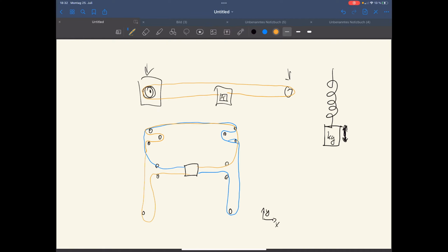So let's assume we want to print a shape like that. And when we are going with our acceleration and speed along that, to that, that to that, that to that. If that is exactly within the time we need here, if that is 1/2f, for example, so f is the resonance frequency, you would be all over the place because the printhead would shake all the time in this direction, and then we would have a shape like this on those walls.